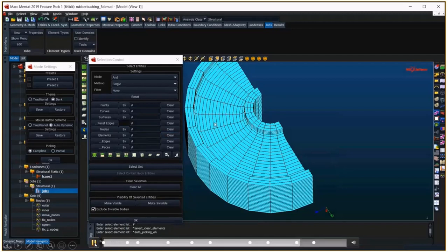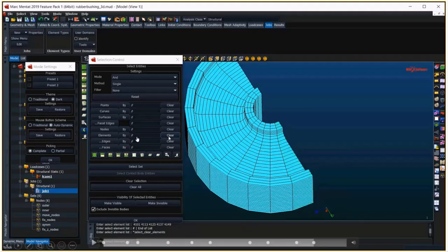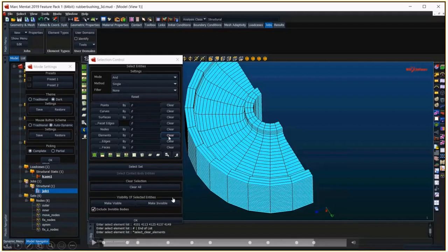So now I'm going to turn it on. And I select that, and it's automatically added. Again, I did it a little fast, but I had 320 elements added almost immediately. No end of list. You can see that if I want to keep adding, or do some other action, it's easy because I don't have to do the end of list. When you're only doing one, maybe it's not as big of a savings, but when you do this regularly over and over again, and your selection is a complicated one to build, it can really significantly improve your ease of use and reduce your time.